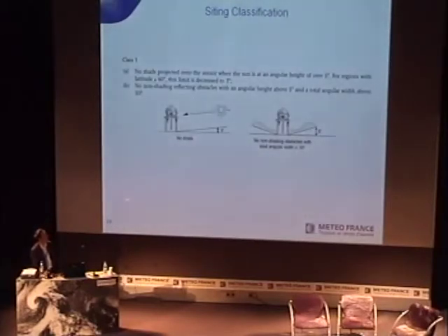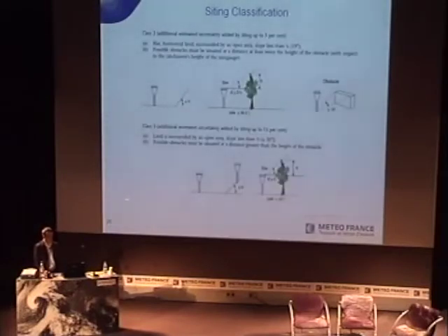Of course, for radiation, you try to avoid any problems of shade on the sensor. This is pretty straightforward. For rain gauges it is a little tricky, because the right rain gauge is a rain gauge with a fence to prevent wind from disturbing the rain going into your rain gauge.